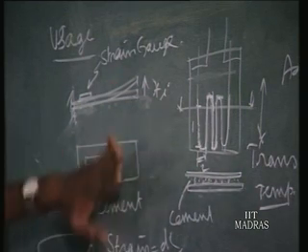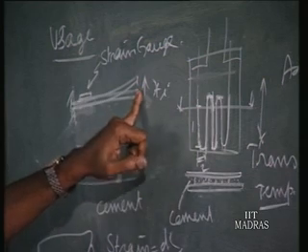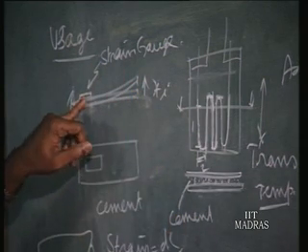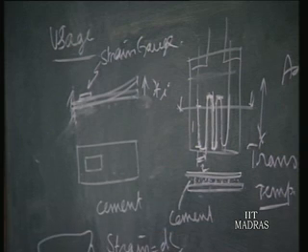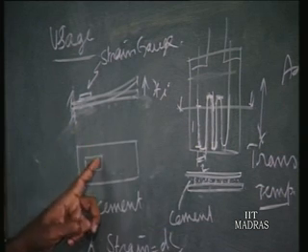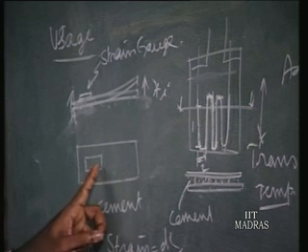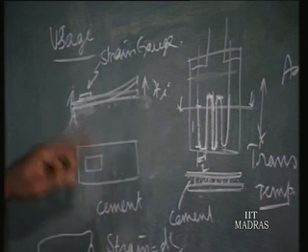All these things are happening without any input signal. Without any input signal, just because there is a temperature increase, resistance is changed as per this equation. Again, it is being pulled due to the difference in coefficient of thermal expansion. Again strain, that is another source.